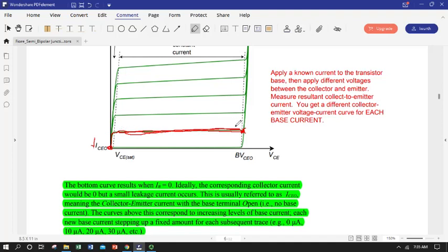So we've got high current increase as we turn up the collector to emitter voltage very early, and then almost a flat line. Okay, well, doggone it, but say I needed more current than this, whatever this was. Say I needed a higher collector current. How do I get it if I can't depart from that red line? Well, what I have to do is turn up my base. And so I would jump to the next line.